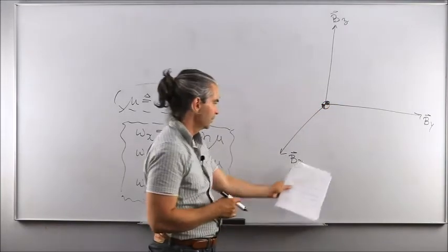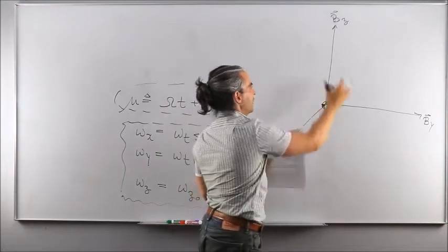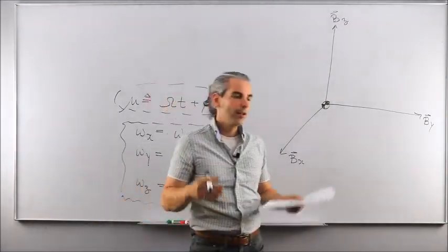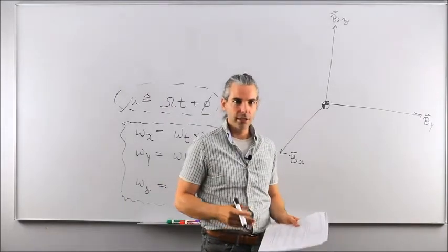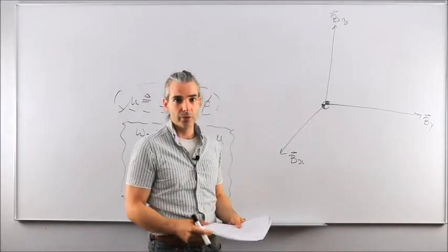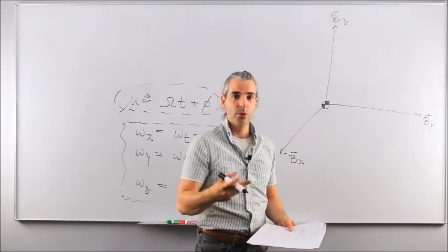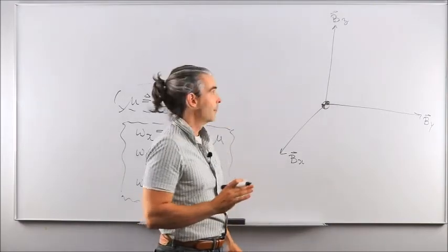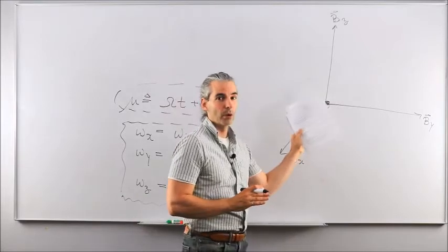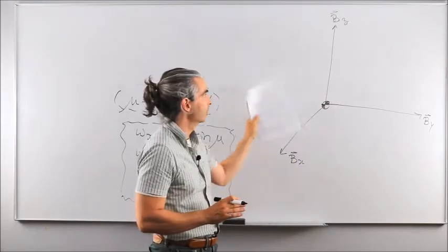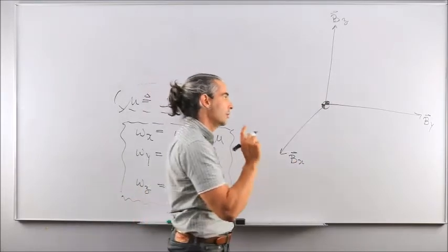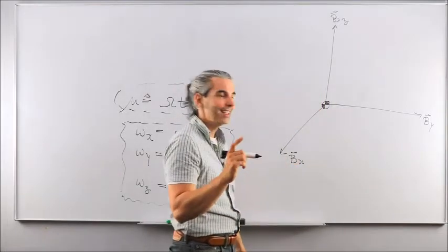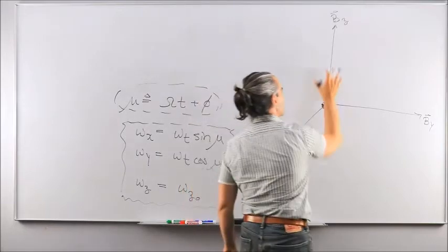So with respect to some inertial reference frame, that body fixed reference frame is tumbling around about all 3 axes simultaneously, based on its initial conditions and based on the geometry of the spacecraft, or in other words, based on the principal moments of inertia. That I do acknowledge. But that's not exactly what we're looking at here, because what we're actually looking at is just the motion of the angular velocity vector seen from that perspective.